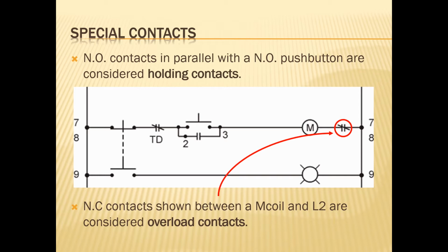But we should be able to recognize my normally closed contacts are my overload contacts, and those are being controlled by my overload heaters that are part of my motor controller.